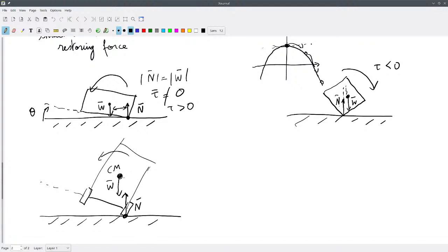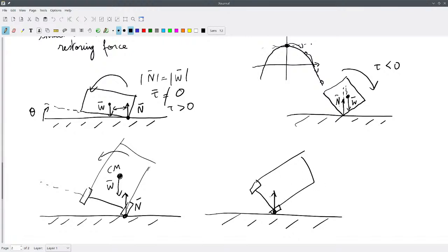If the weight goes to the right, or to the outside of the two tires, so if we now have something like this, and the normal force is applying here, and the weight is now applying here, then of course the truck will tip over, and it will go to the next stable equilibrium, which is the one where the truck is entirely flat on its side.